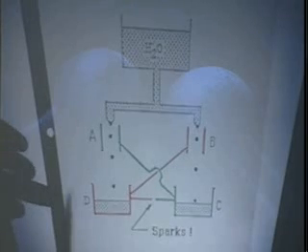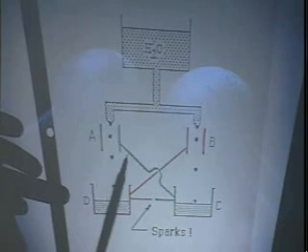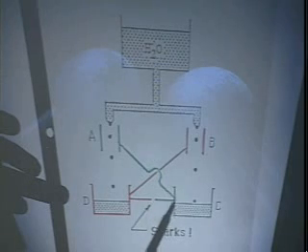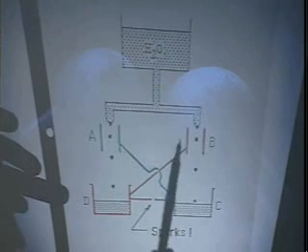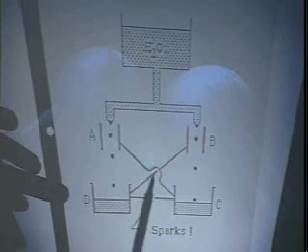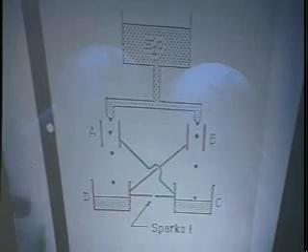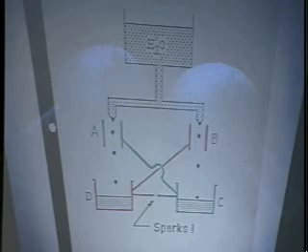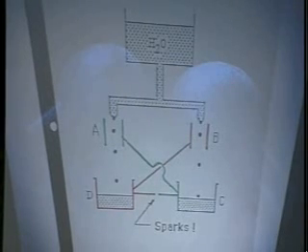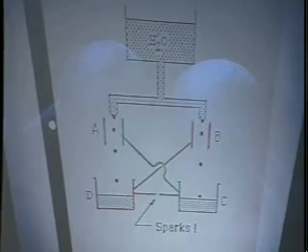And now comes the key point. This conductor here, A, is connected through a conducting wire with C. And the conductor B, the paint can, is connected with a conducting wire to this trash can D. You let the water run for a while, and you will see between these 2 points here, sparks. Even when the points are as far apart as, say, 5 millimeters, when you're talking about a potential difference of something like 10, 15,000 volts, you will see the sparks. And you wait, see another spark. And you wait, and you see another spark.